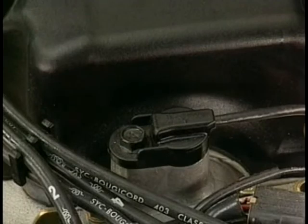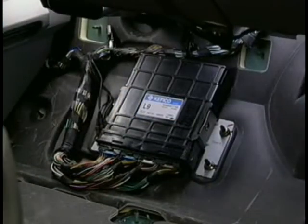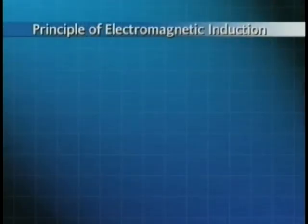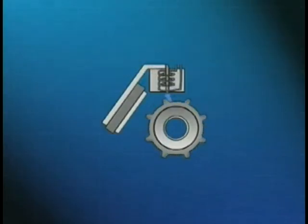By far, the most common type of crankshaft position sensor in use on today's vehicles is the magnetic pulse generating sensor. Magnetic pulse generators use a timing disc and a pickup coil to send a voltage to either the ignition module on older systems or to the powertrain control module on current systems. The pickup coil operates on the principle of electromagnetic induction that says voltage can be induced when a conductor moves through a magnetic field. A permanent magnet in the pickup coil is used to create a magnetic field.